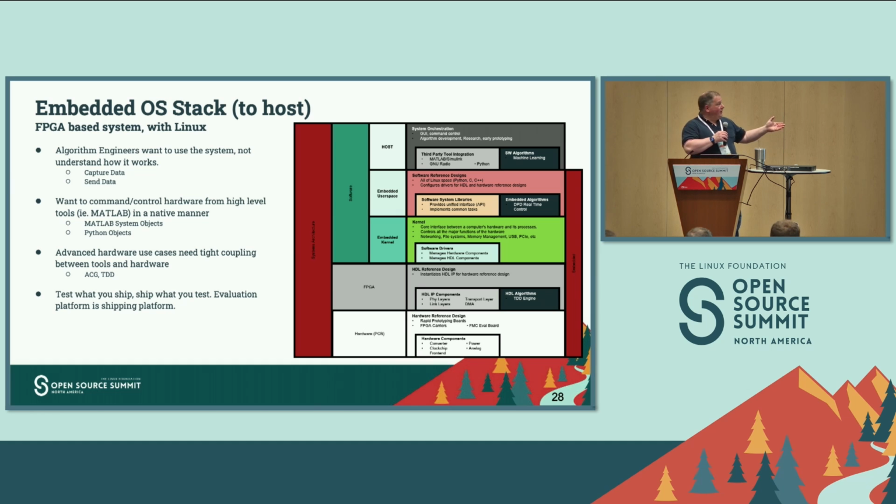So, for example, if you are a device driver person, you can write the device driver and then just test it with everybody else's user space. You don't have to write your own data capture application, making FFTs and applying window functions and all the things you didn't like to do, which is why you write device drivers. Or vice versa, if you're the algorithm developer, you can focus on those pieces and not have to worry about the bits and registers, trying to figure out reading data sheets. Because hardware data sheets are written by hardware engineers for hardware engineers. They are not written for software people.